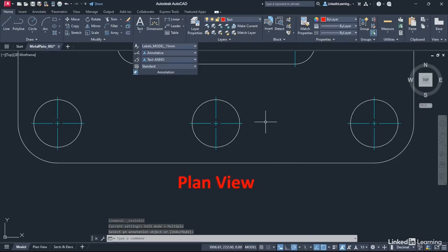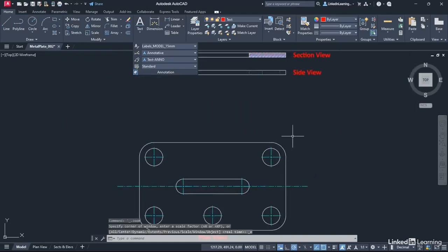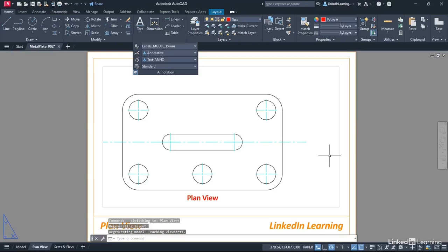Double click on the wheel now to zoom extents, and you'll see now that we've got some nice labels there on our views in the model tab. Click now on the plan view layout tab, bottom left of the screen. You'll see we've got a simple plan view title block ready to go. And what we're going to do is adjust this viewport ever so slightly and bring it down. And then we're going to place some notes text in the top right corner of our sheet here, ready to obviously communicate our design intent with our plan view sheet.